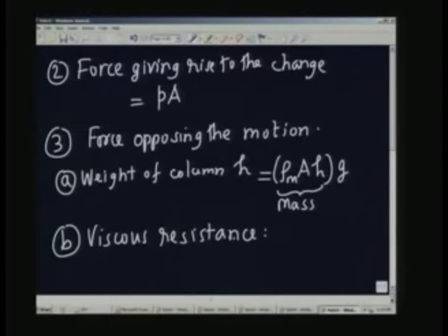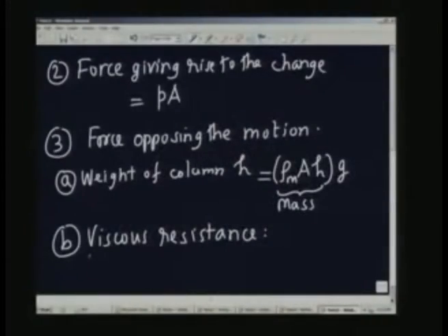the definition of resistance. We know that resistance is equal to the pressure drop divided by the mass flow rate. So, the pressure drop multiplied by area is a force. So, what I want is delta Pf multiplied by the area of cross section. Okay. So, viscous resistance is nothing but delta Pf multiplied by the, I am sorry, not the mass flow rate, the area of cross section.